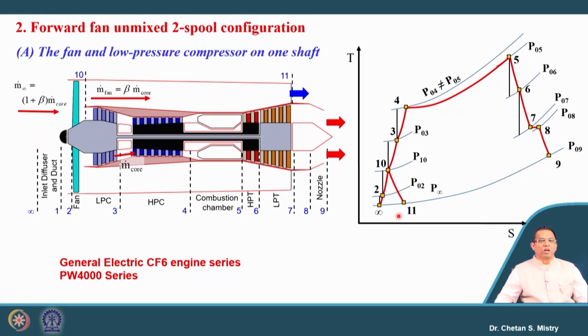So, I am sure you are now familiar with what we are discussing in terms of representing the cycle on the TS diagram. So, it is preferred that based on the configuration given to you, you just plot the line diagram, and from that line diagram try to plot your TS diagram. So, it will not give you any wrong information or you will not get confused.